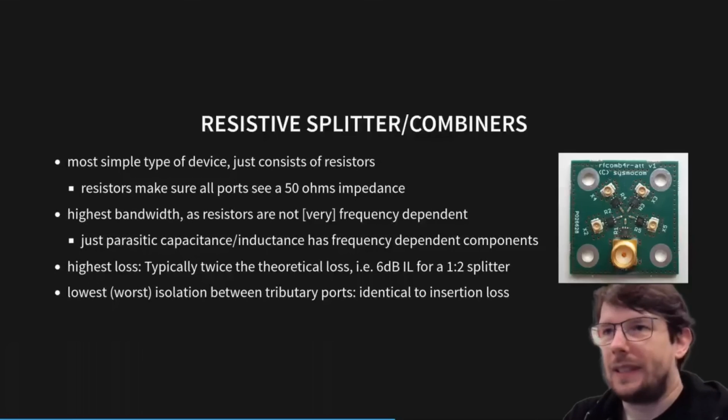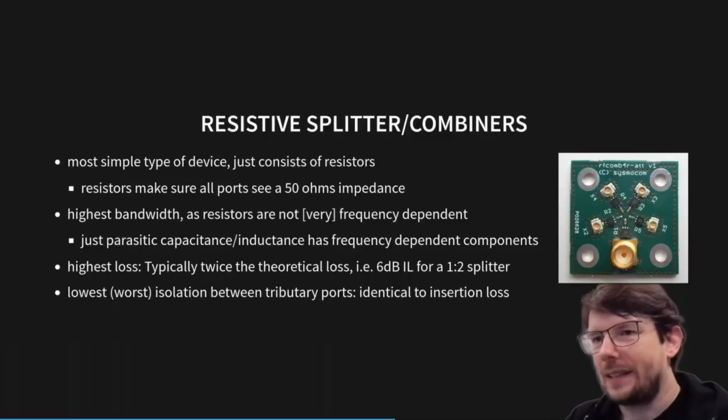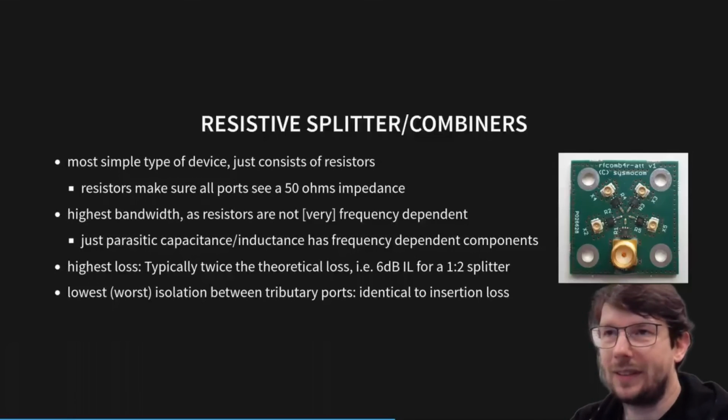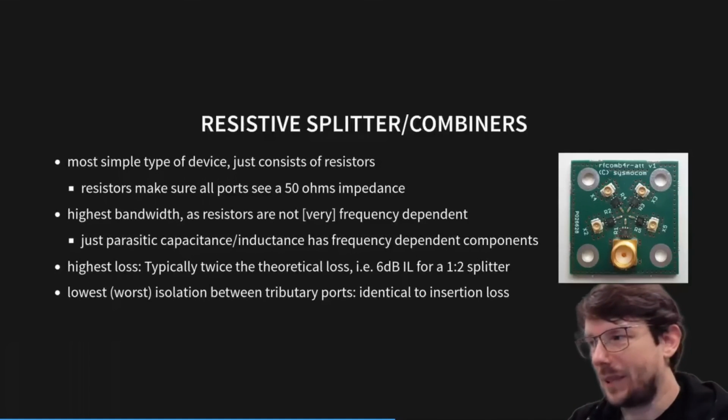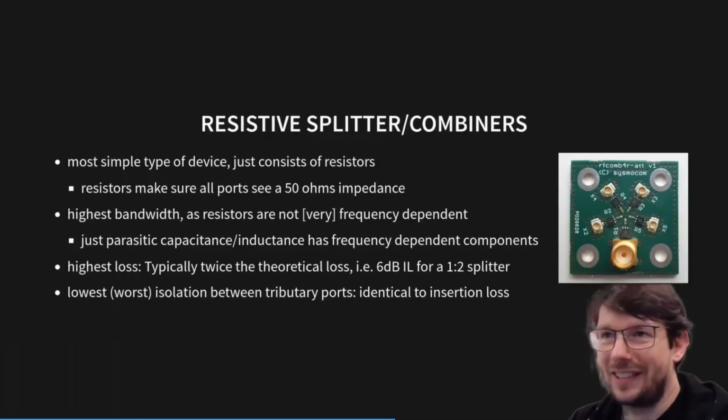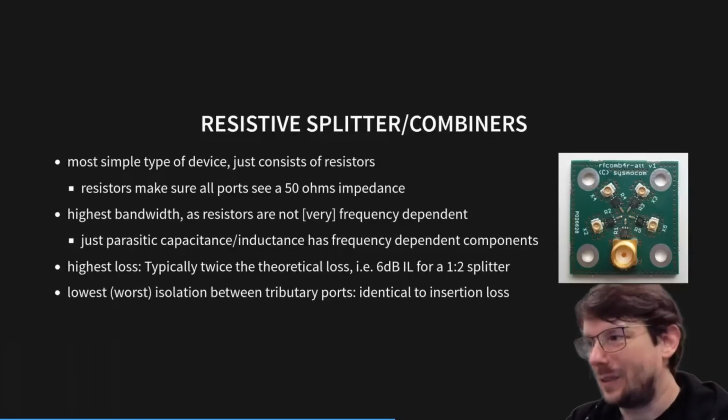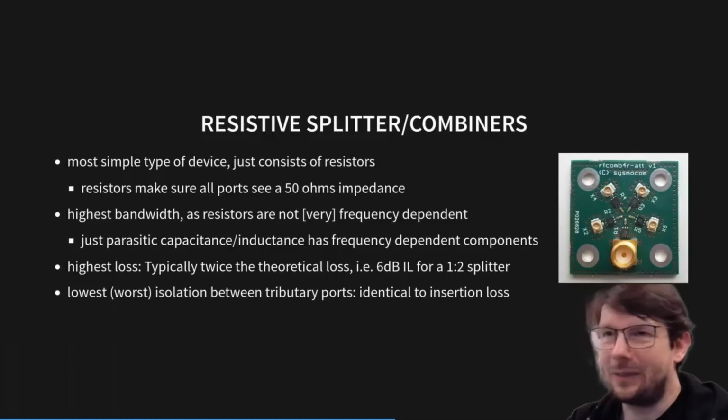Maybe also, if you actually build something like that, I didn't say anything about measurement. So the most useful tool to have is an RF power meter, of course, in such a setup, or a spectrum analyzer, or both, so you can actually see what kind of signal levels you're getting. What's also very useful to have is a network analyzer. Doesn't have to be a vector network analyzer here. In this case, it could even be a scalar network analyzer.